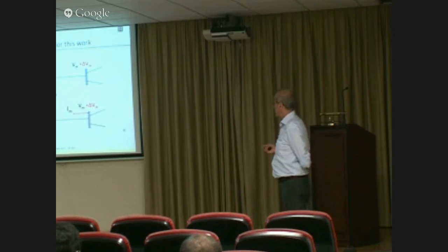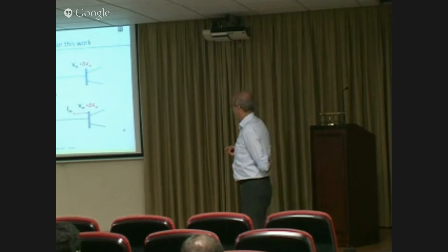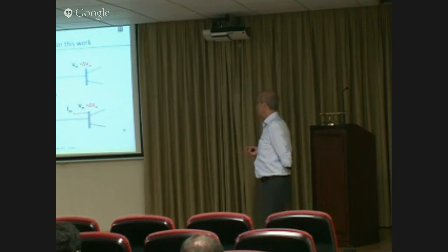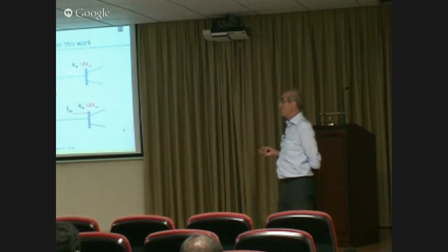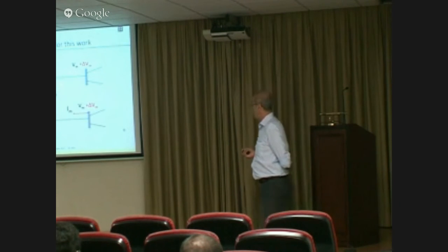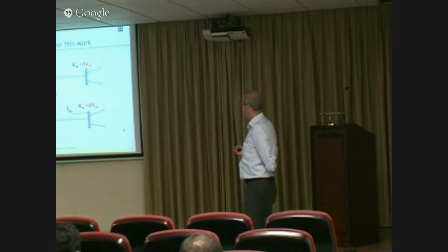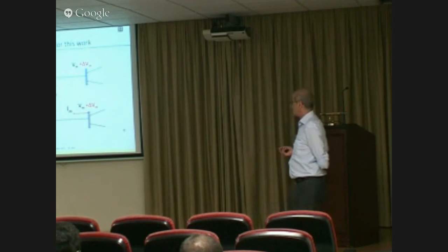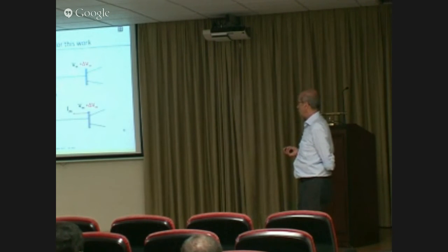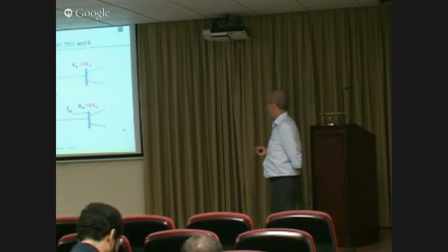And this injected current, which is a negative current actually, will of course change the solution. And so the voltages will go from the pre-fault values, Vk and Vm, to the post-fault values, which are this plus delta Vk and that plus delta Vm. So that's the picture. So this is the pre-fault in black and post-fault in black and red.